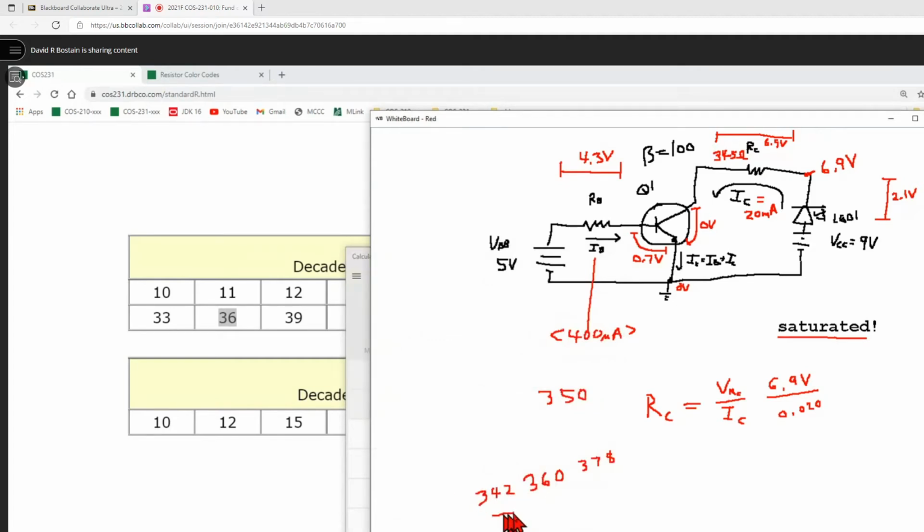Then we do our same exercise. We calculate the current and the wattage. We make sure that this current is not too big. We make sure that current's not too small. So this guy has to be less than 25 milliamps. This guy has to be bigger than 15 milliamps. This guy has to be the wattage we're going to actually size our resistor based on. And then we're going to be able to go to the store and buy. We could get the color code for that. We've done that already. So now we'll have identified this particular resistor.